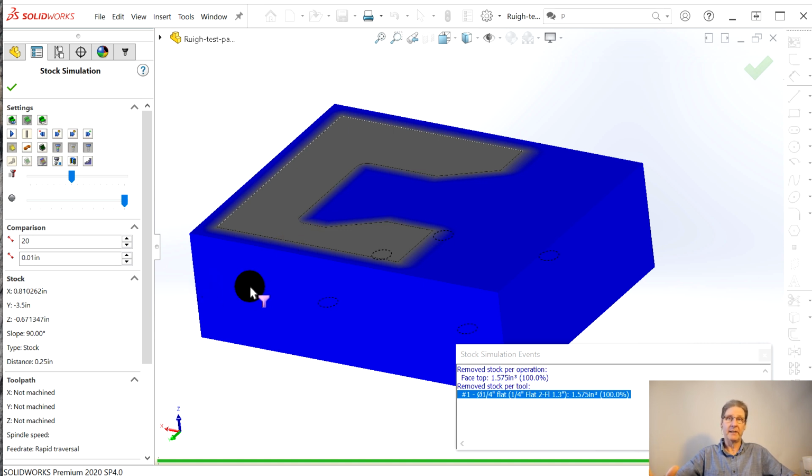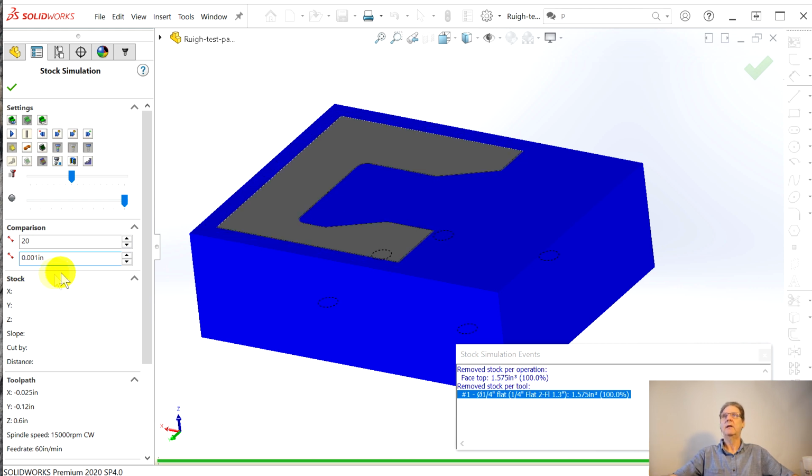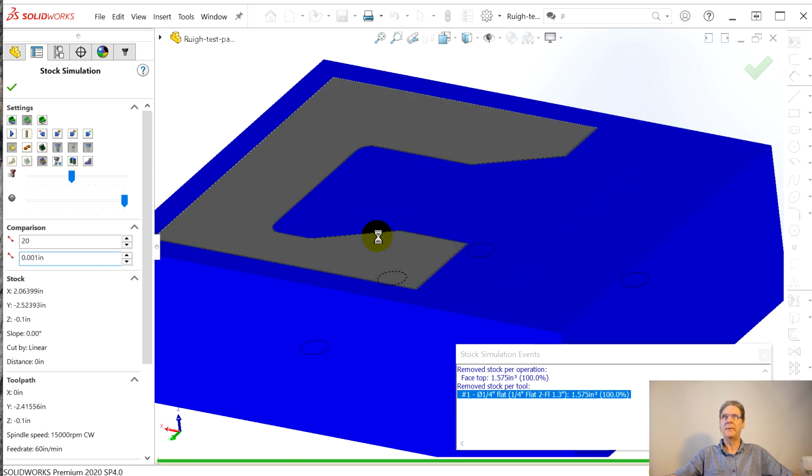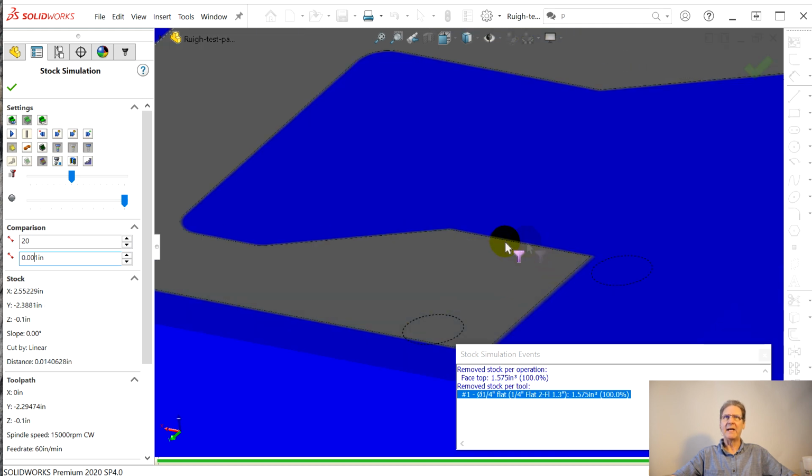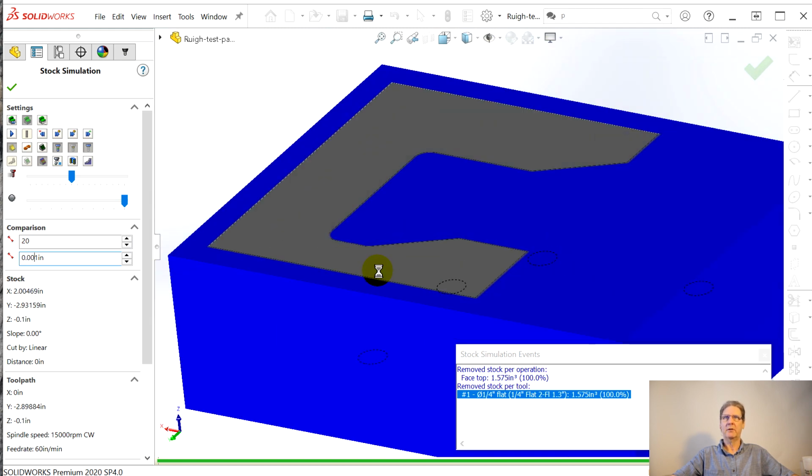If those were colors, I'd be able to say, hey, it's green where it's supposed to be green, and then it starts changing colors. And I don't need 20 levels. What I found that makes my blood pressure lower is just add a 0. And then boom, it gets a hard, sharp edge that's like, okay, that I believe it's cut the top of the part correctly.